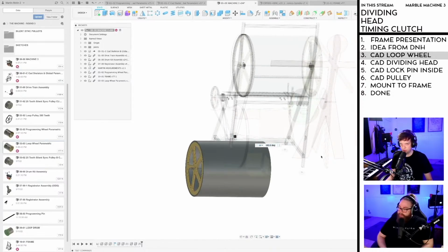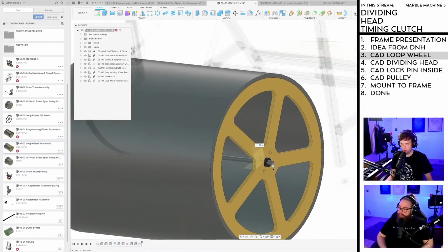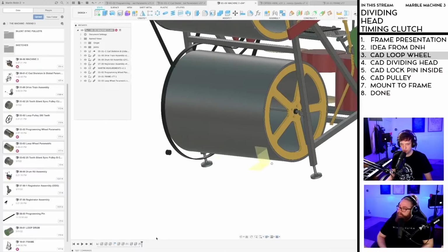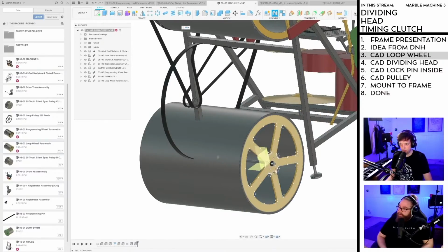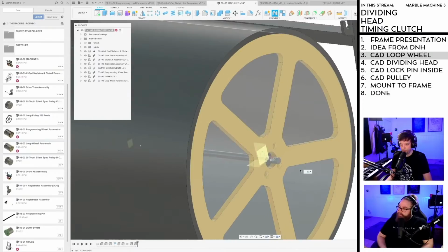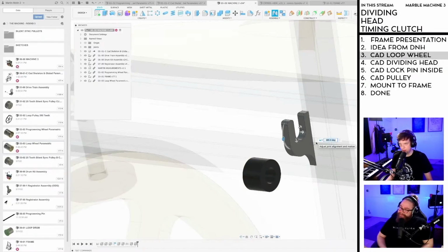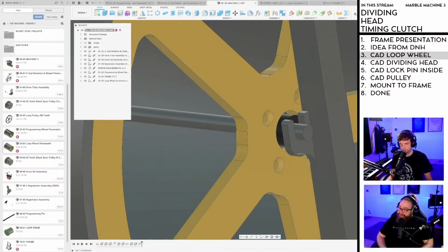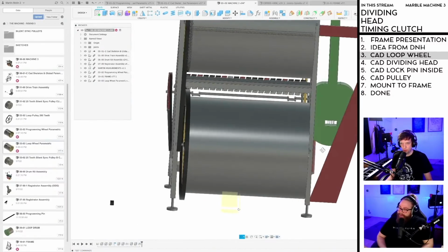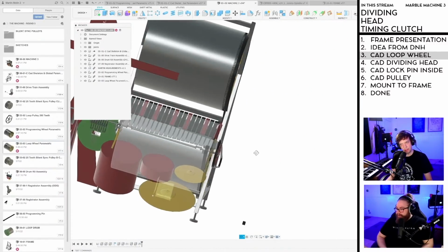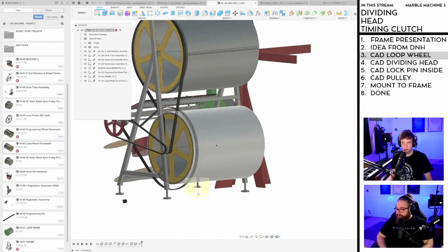I'm gonna deselect the first one. See if actually gonna deselect both. Delete the joint. Let's join it here. Yeah, now the belt is clearing and it's lining up perfectly with the side of the drum.